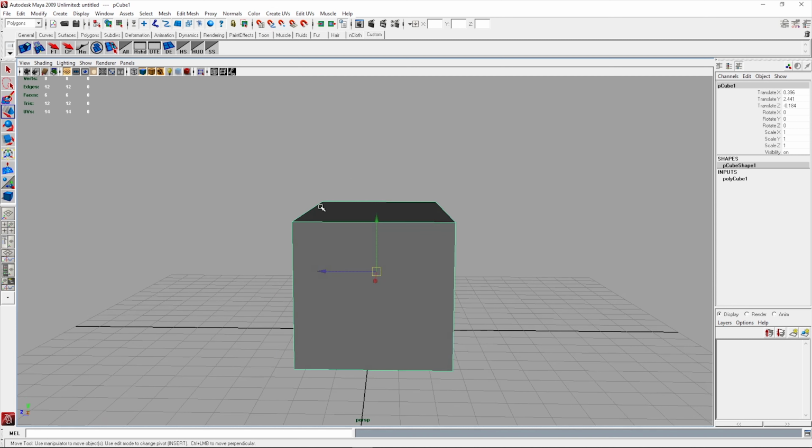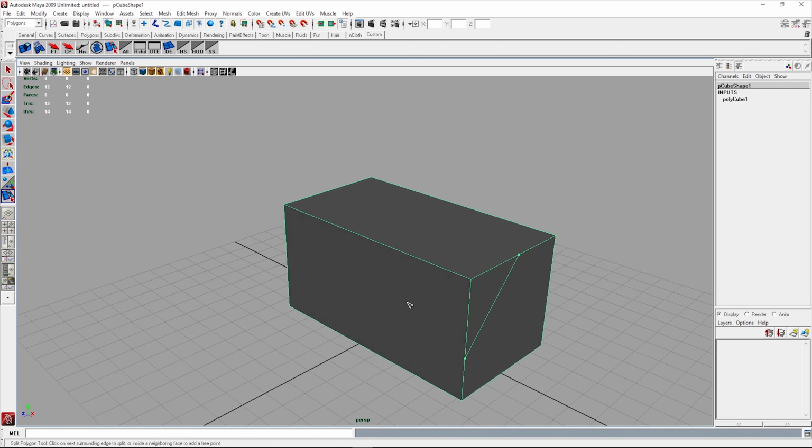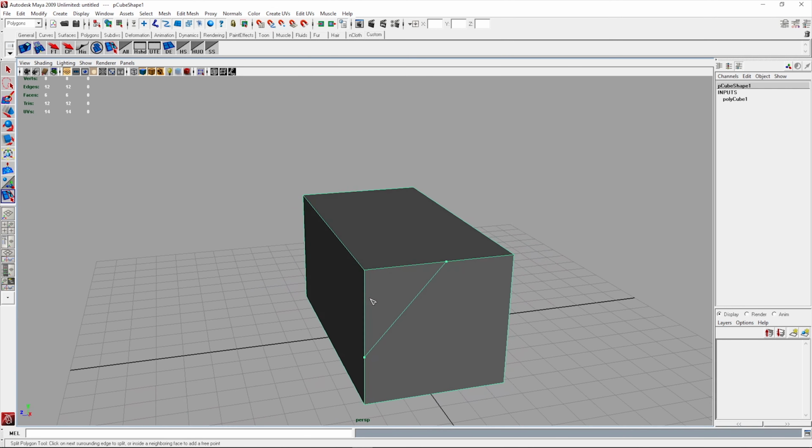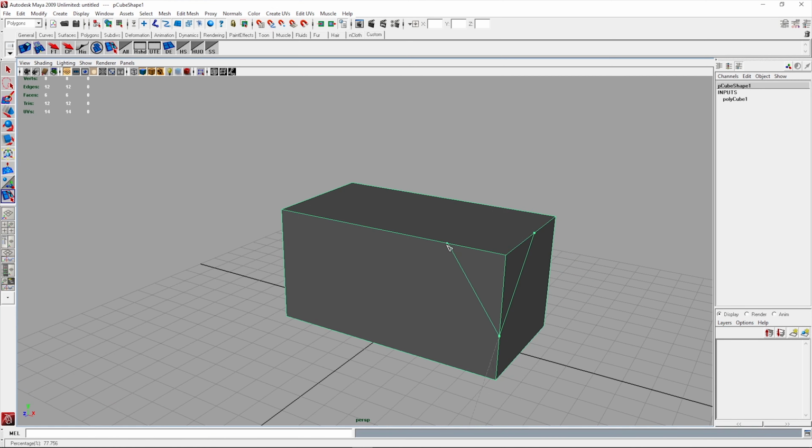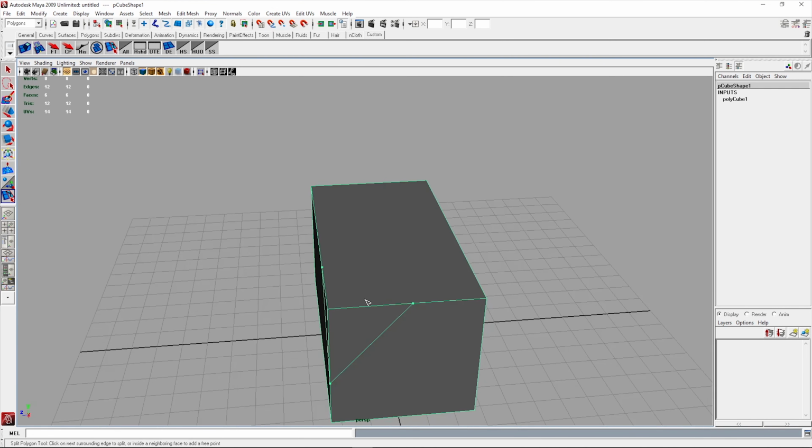Right, okay. Selected the object, hit the cut tool, and now while it says that, click and drag on the first edge. You can click on it and drag the edge, the little dot along, which tells you where it's going to make the first cut. I make a cut here, and a cut here, and then I'm holding down the Alt key and left dragging while I'm still in that tool, and then I'll drag along this edge, and then I'm going to complete that line and cut along here until I reach that edge.